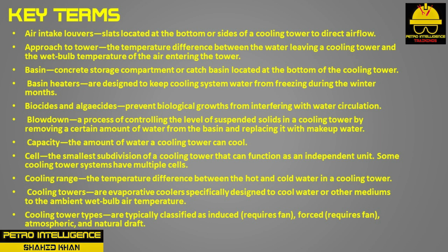Air intake louvers are slats located at the bottom or sides of a cooling tower to direct airflow. Approach to tower is the temperature difference between the water leaving a cooling tower and the wet bulb temperature of the air entering the tower. Basin is concrete storage compartment or catch basin located at the bottom of the cooling tower.